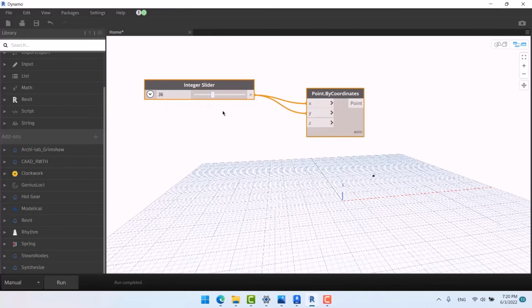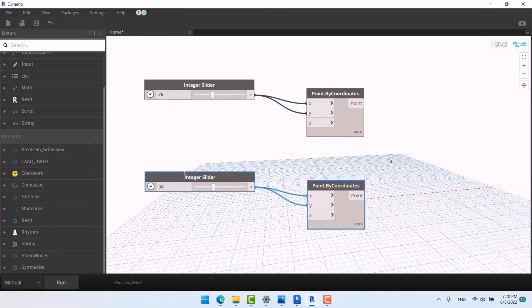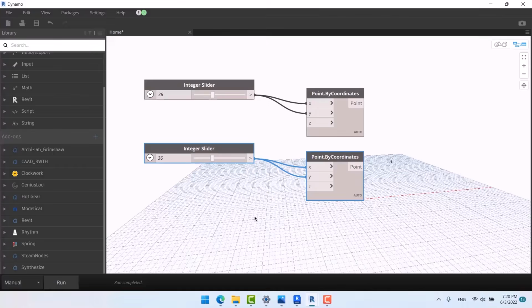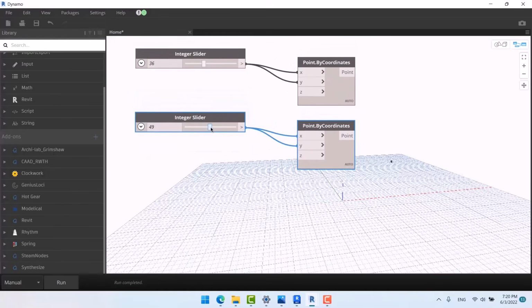if I change this, as you can see, the wire and the round of nodes all become orange. The rule that I told you before applies here as well. If you create a new node and you change it, it doesn't become orange. You should click on run once to recognize it first. From that moment on, it will show you the changes with orange color.